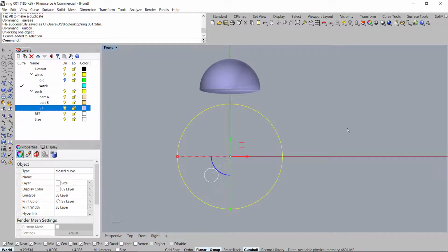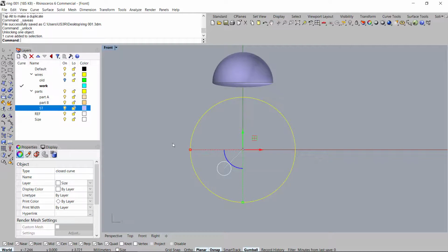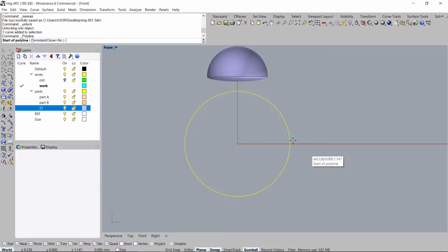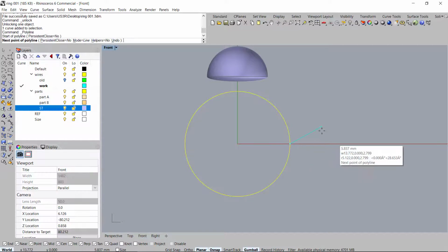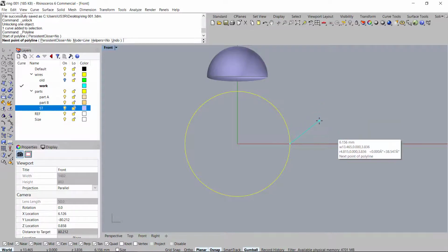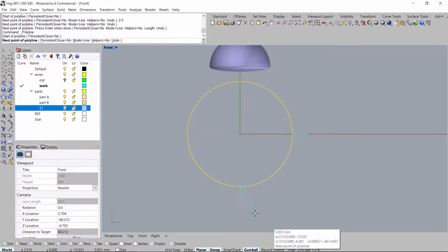I'll select the finger size guide here. I do want to create the curves that will determine the width of the shank. So I usually go with a comfortable size on the side. You never want to go too far out, like 3 or 4 millimeters. It becomes very uncomfortable if you plan to wear this ring every day. So a safe number is anywhere between 2 to 2.5 ish, so let's go with a safe number, 2.5. Okay, and for the bottom I'll do the same thing, but this time I'll go with a distance like 2.